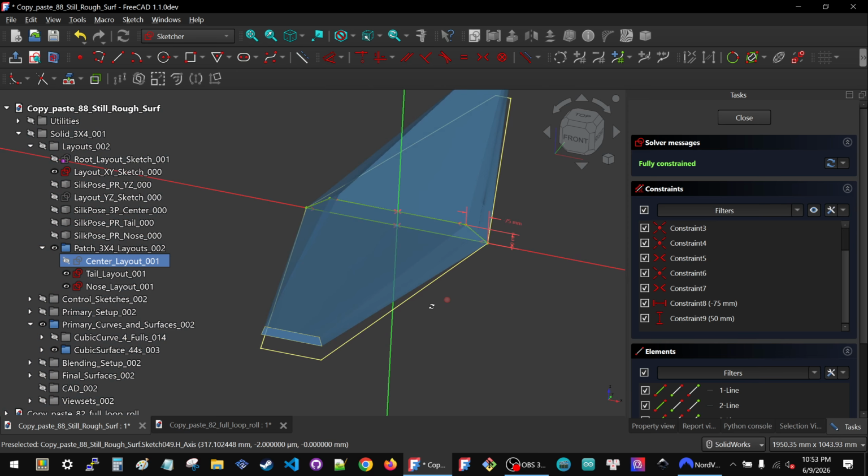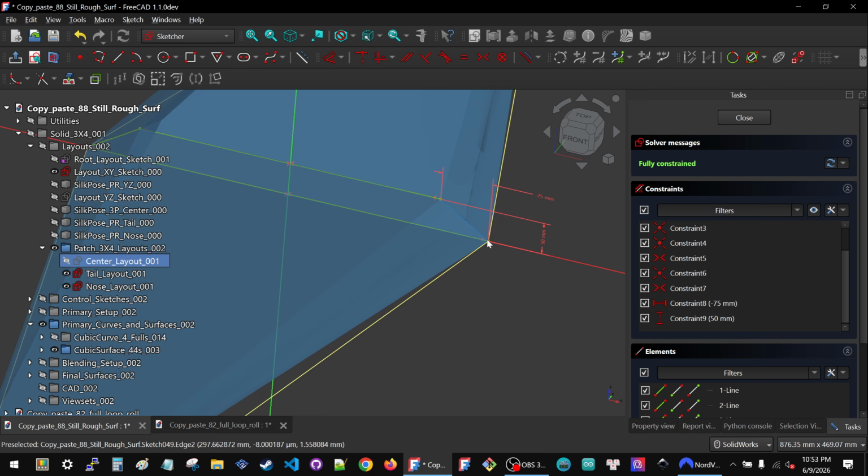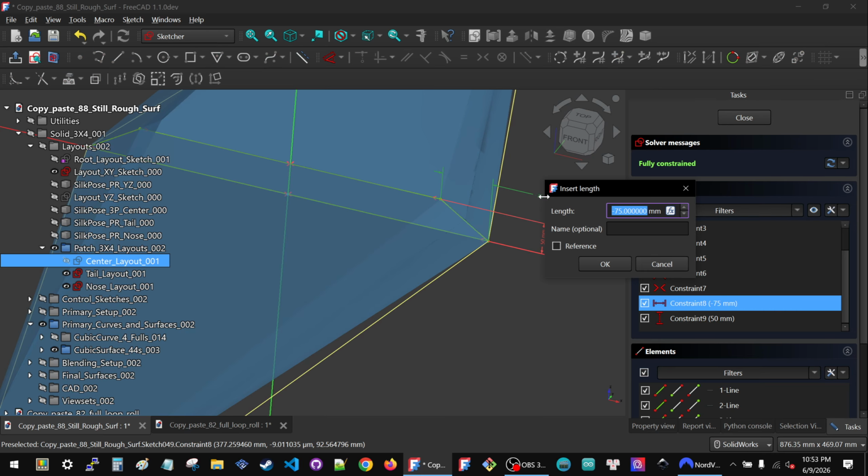And that's really useful because I'm driving from my layout to the bottom line of this sketch. And then after that, once I've established where this point is, I'm saying the top of the rail is always inward from this point. So always negative. And then the height is always positive. So this is really useful. Let me show you how that works.